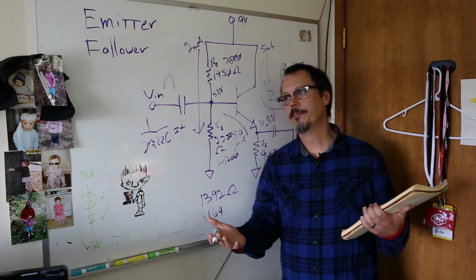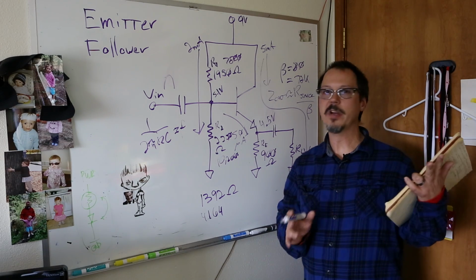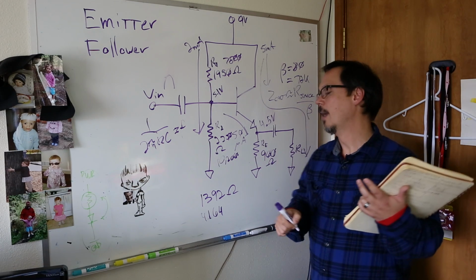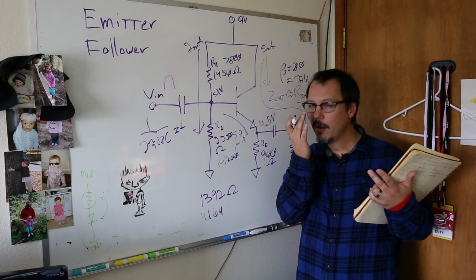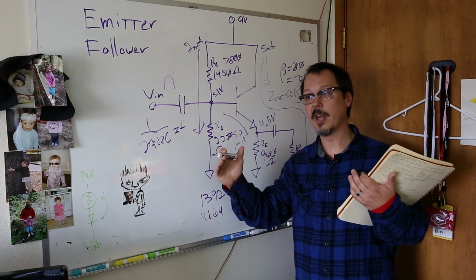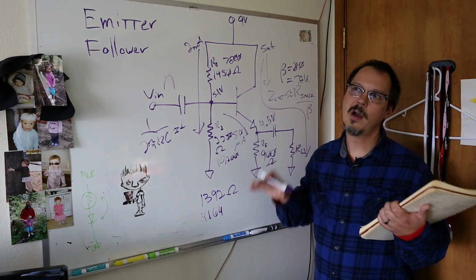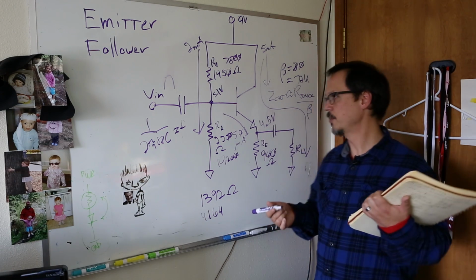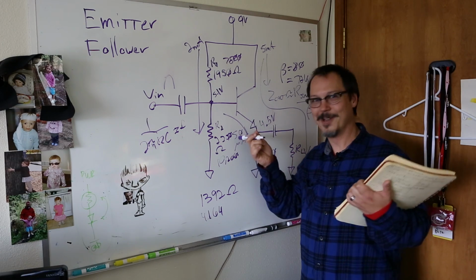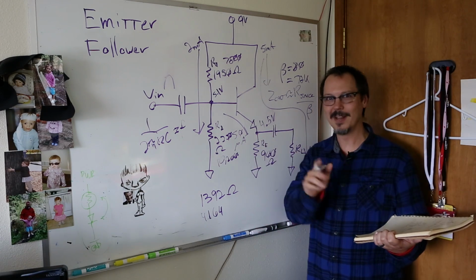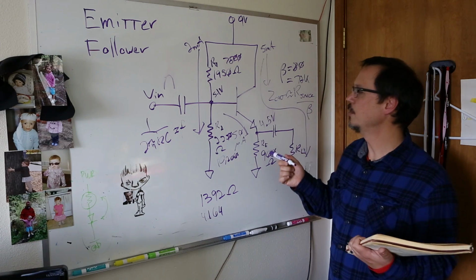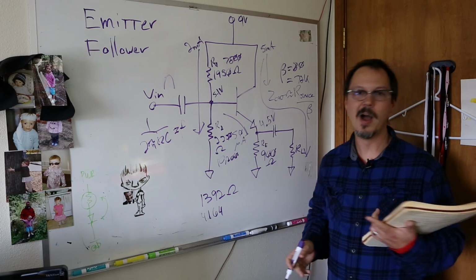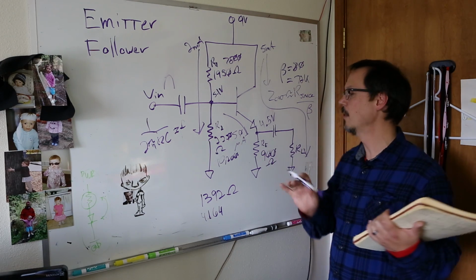Well, you wouldn't necessarily. The 2 circuits that I've shown you so far are not very interesting to me. The most interesting one is going to come when we talk about common emitter. The reason you would use that one over an op amp is that it gives you voltage gain and current gain. Also, op amps are optimized for linearity, whereas with a transistor you have to work really hard to make it linear, which sounds like a downside, but it isn't always, because it allows you to really jack with your signal in interesting ways. You can add harmonics, you can do mixing, it becomes kind of wacky.